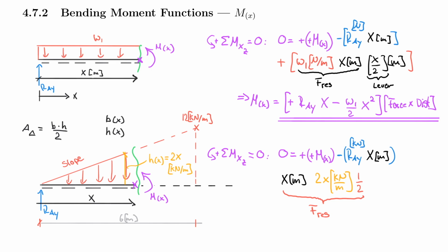So now the question is, what is the lever arm of this triangle? And of course, you know that the lever arm for a triangle is always at the 2/3 or 1/3 side, and 1/3 from the heavier side. And this is really where we're taking the sum of the moments about. So I really need to look at x divided by 3, if you will, here.